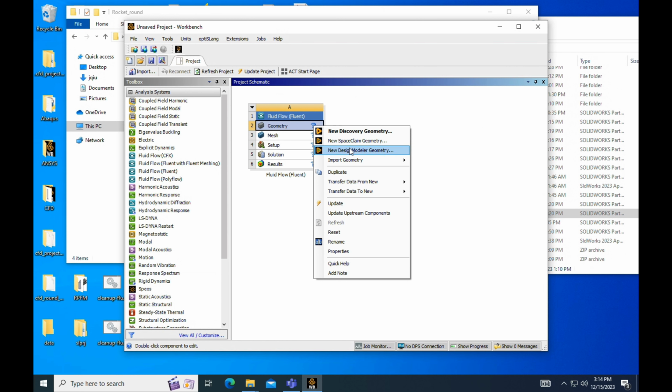We're done. We can set up our velocity inlet. This is where the direction of the arrow will be coming from. And then we'll select our pressure far field for the top and bottom. And finally, we'll select pressure outlet for the end.